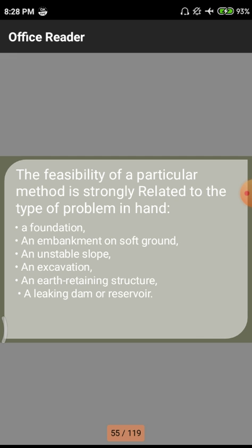Because if there is no slope, the dam will be overturned by the water forces, which are huge at the peak of storms. To negotiate those forces, we have to maintain slopes. Next is excavation. Excavation is normally the primary work when we go for a construction.